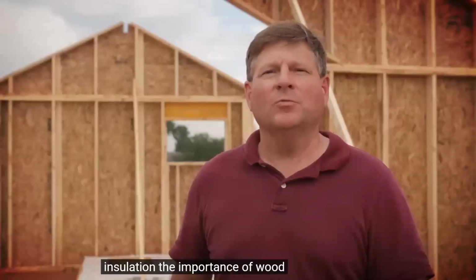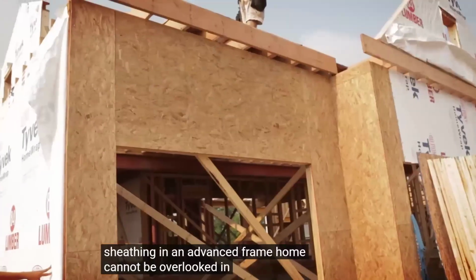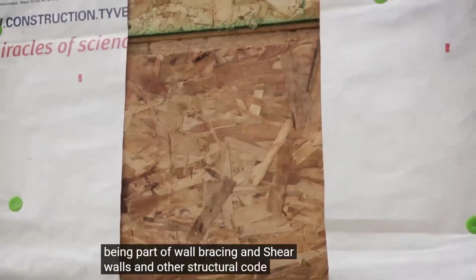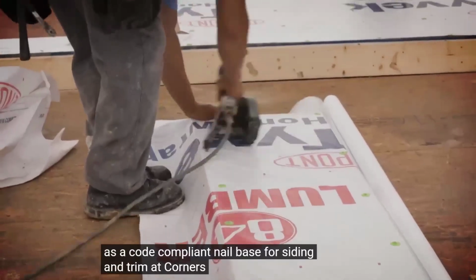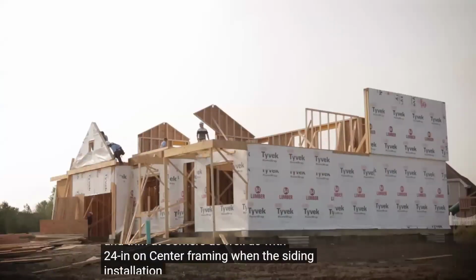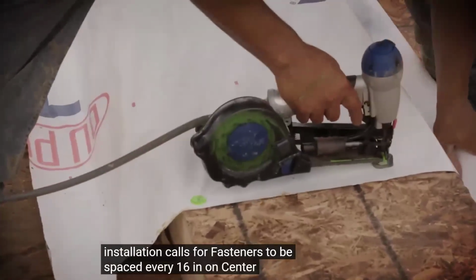The importance of wood wall sheathing in an advanced frame home cannot be overlooked. In addition to being part of wall bracing and shear walls and other structural code requirements, the sheathing also serves as a code-compliant nail base for siding and trim at corners, as well as with 24-inch on-center framing when the siding installation calls for fasteners to be spaced every 16 inches on center.